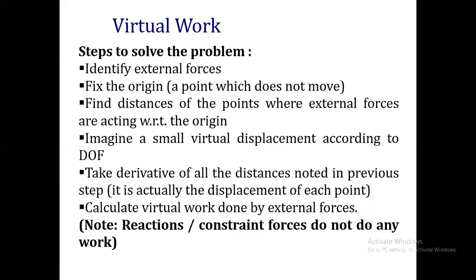Also we need to take the derivative of the distances which we have computed earlier, and these derivatives will give us the displacement at each point. The force acting at that point multiplied by the virtual displacement will give us the expression for virtual work done due to that particular force.